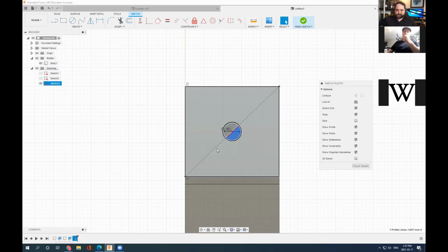Hello. And hey, Wilfred. What's going on? So I have the circle, but I made a normal line, not a construction line, to make it. Then I got rid of the line to catch up, and now I don't have the line, and I couldn't get that dimension tool to work to change the radius. Okay, yeah, I don't know why it wasn't working for me either. Something's going on anyway. They just did a patch update, so I don't think it's that, but it might be.